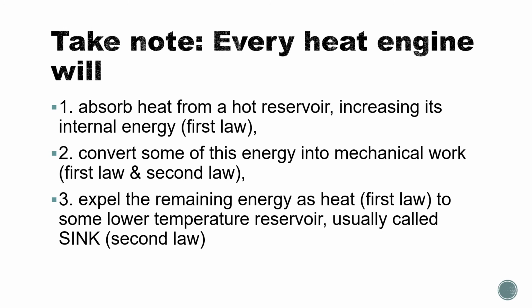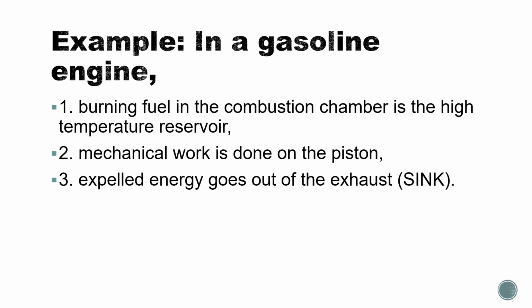The first and second law of thermodynamics are applied in heat engines. Every heat engine will absorb heat from a hot reservoir, increasing its internal energy. First law. Convert some of this energy into mechanical work. First and second law. Expel the remaining energy as heat, first law, to some lower temperature reservoir, usually called sink, second law. Like for instance, in a gasoline engine, burning fuel in the combustion chamber is the high temperature reservoir.